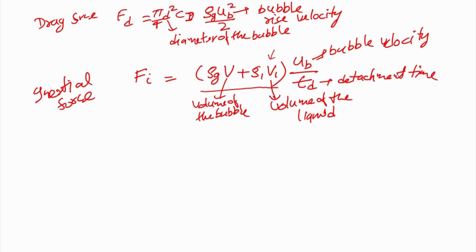Now, these are the forces which are important to determine the bubble size, because the bubble is growing on the surface, buoyancy keeps on increasing, the drag force will act once it is lifted up, the buoyancy is increasing, gas momentum flux is increasing, and the inertial force is trying to stop the detachment. Completely together they will determine the size of the bubble. Obviously, surface tension is also playing a role.